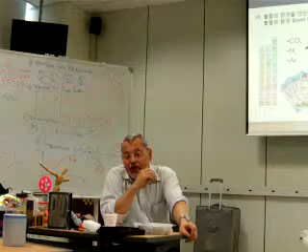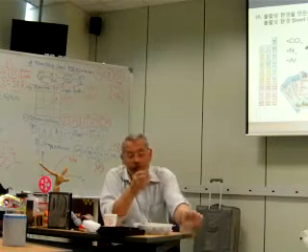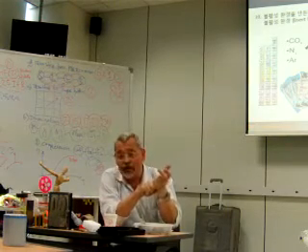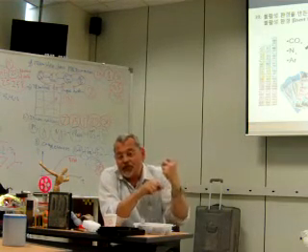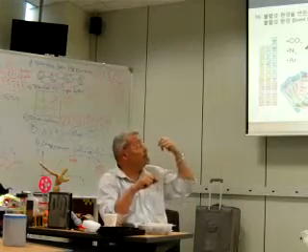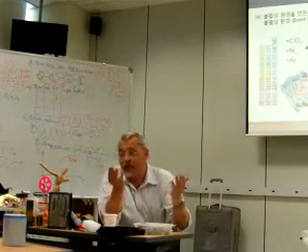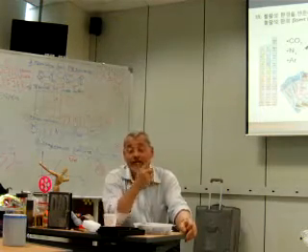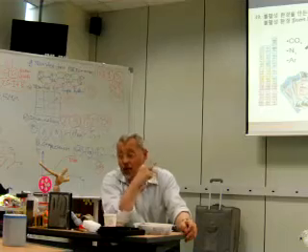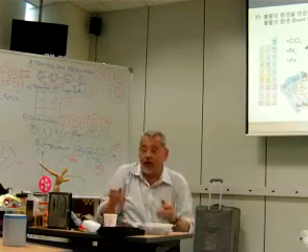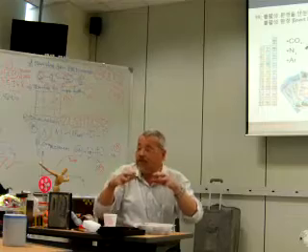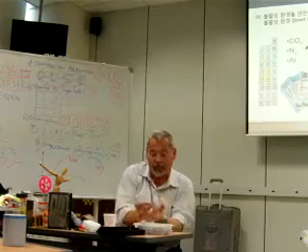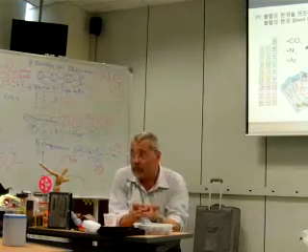But we can use inert gas to extinguish fire. For example, nitrogen and argon are applicable for extinguishing fire. But for extinguishing fire, we can also use a non-inert gas. We can use CO2. CO2 is suitable also because CO2, like nitrogen and argon, has big density, and when you use a gas with big density, the gas will fall down and remove oxygen from the point of fire, and it is the principle